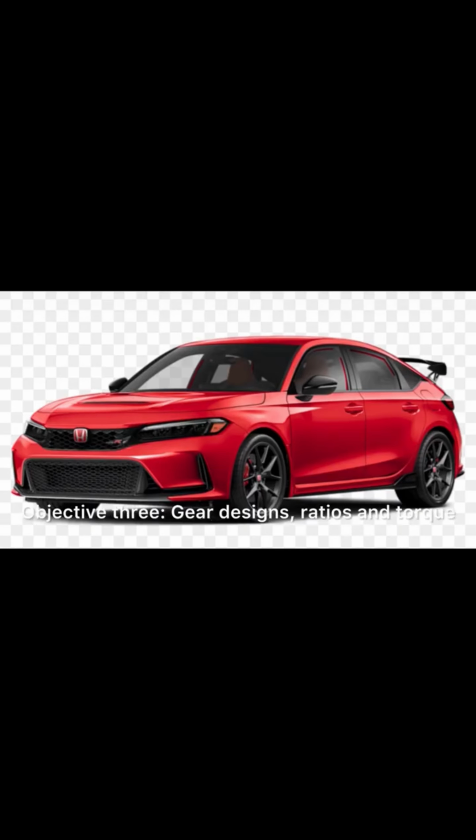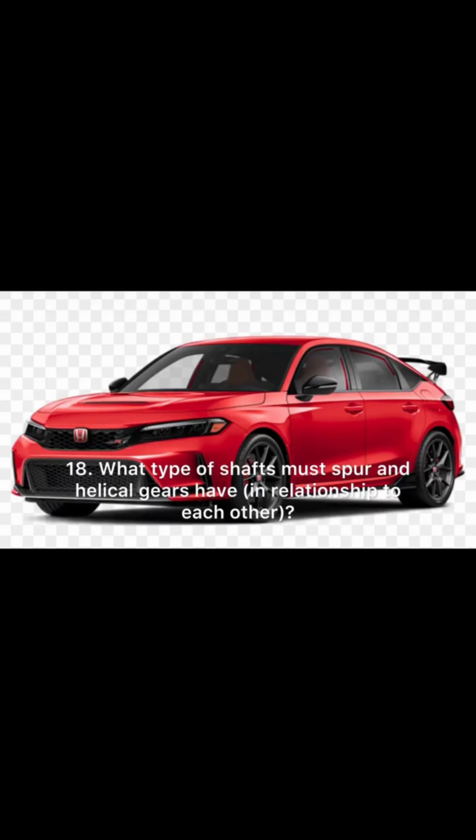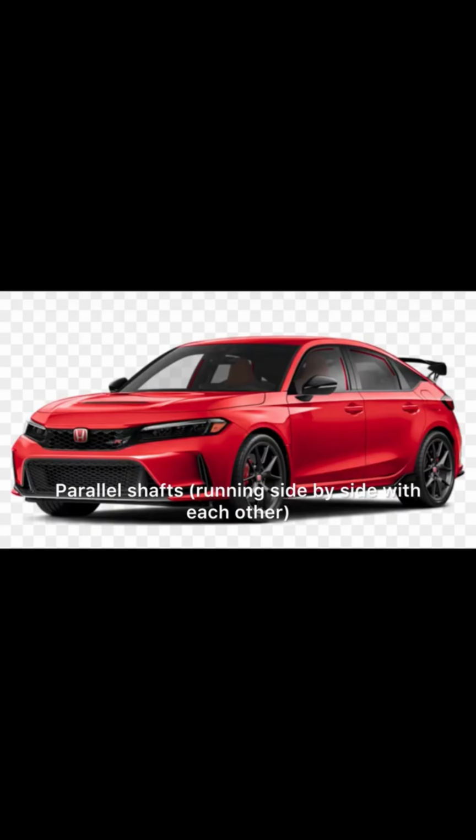Objective 3: gear designs, ratios and torque. 17. What are the two most common gears used in a manual transmission? Spur gear and helical gear. 18. What type of shafts must spur and helical gears have in relationship to each other? Parallel shafts running side by side with each other.